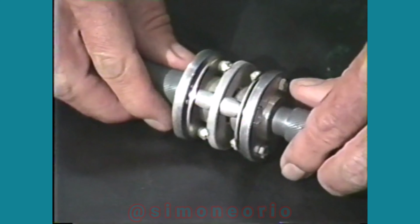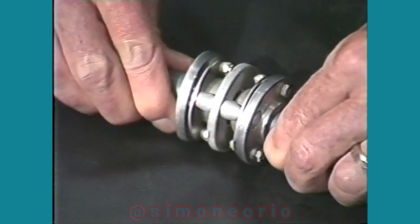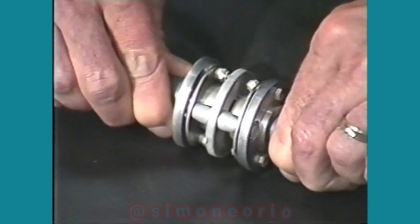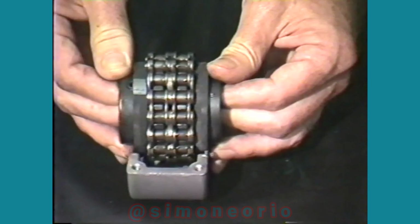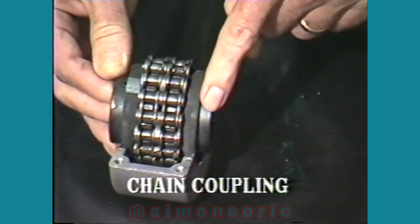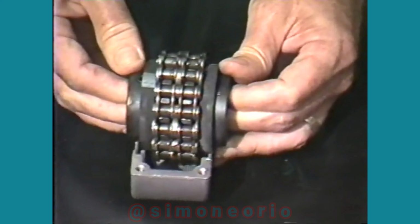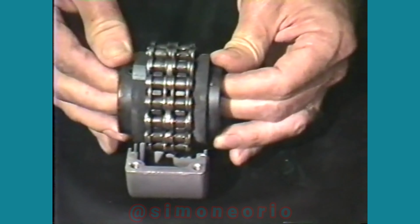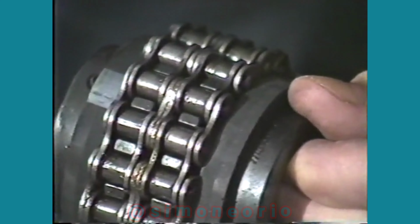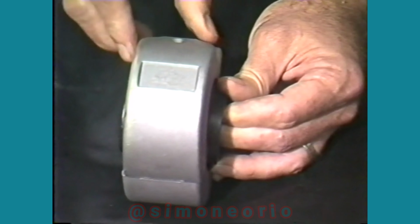The all-metal flexible coupling gains its flexibility by allowing the coupling components to slide or move relative to each other. Four common types are the chain coupling. It consists of two sprockets with a piece of double chain wrapping them. Shaft misalignment is accommodated by clearances that exist between the chain and the sprocket teeth, and clearances in the chain itself. A cover may be installed over this assembly.